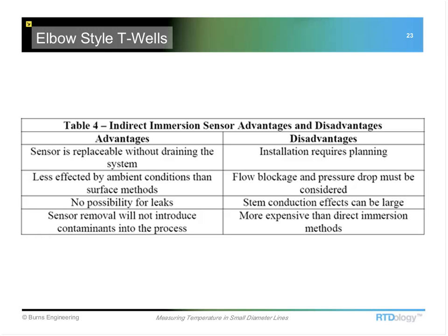Bill, a couple things. One, just to follow up on what you're talking about with the sanitary wells: it is in fact a sanitary application when you use one of these sanitary wells. The sensor that then goes into that well, because it doesn't have product contact, typically is a little less expensive sensor than if you needed to use an actual sanitary sensor with an electropolish finish and a sanitary cap.